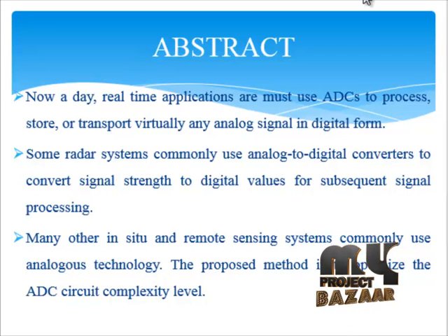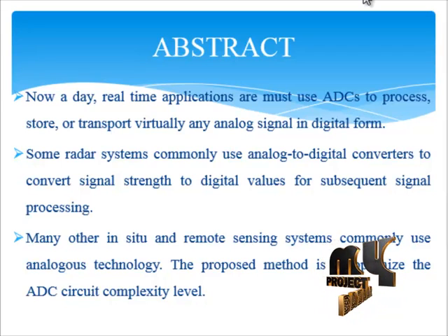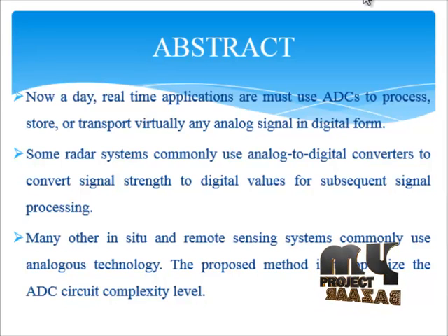The ADC we have fabricated in the 180 nm CMOS process, and we implemented the ADC with an improved SHA and optimized bootstrap switches to achieve high sampling linearity over the input frequency range. The main challenge of the IF sampling ADC is linearity distortion at high input frequencies. The SFDR is of great importance in wireless communication, for detecting weak and peak signals.